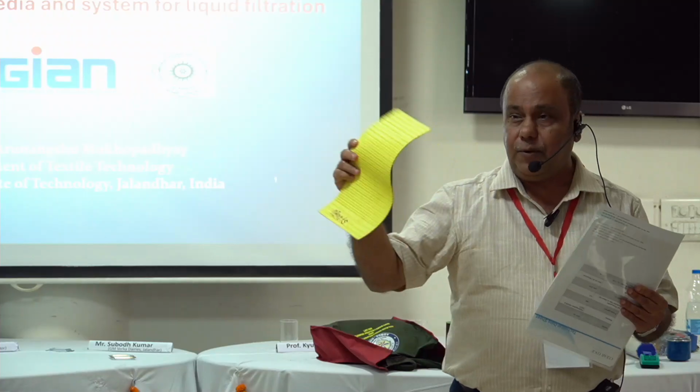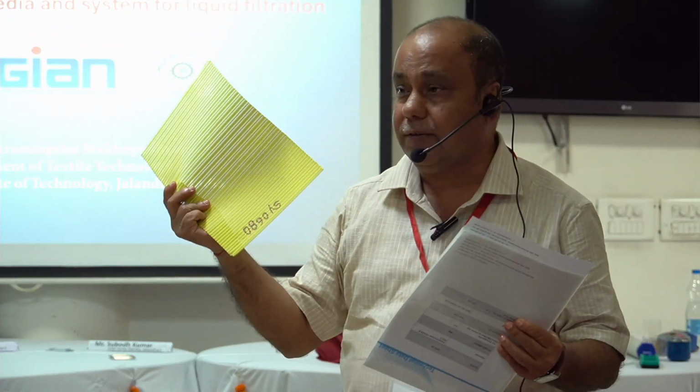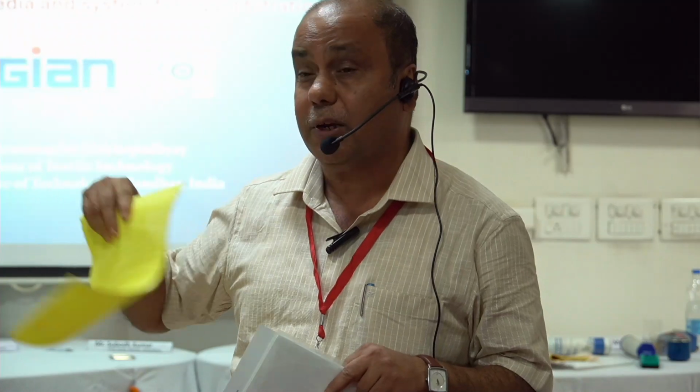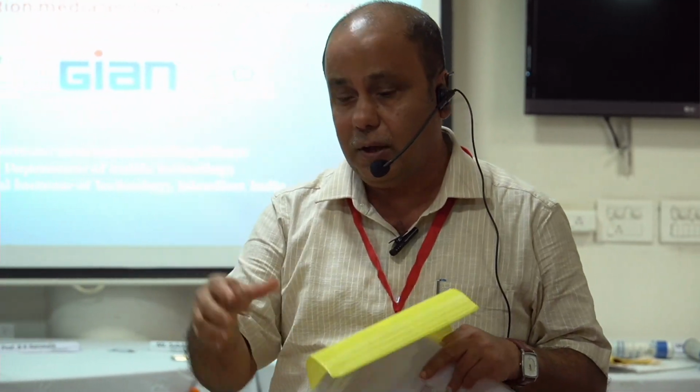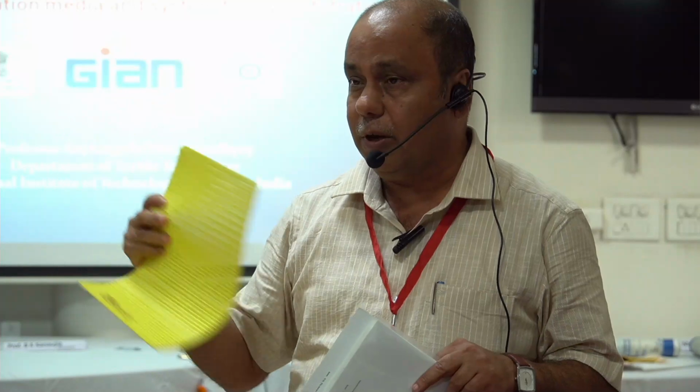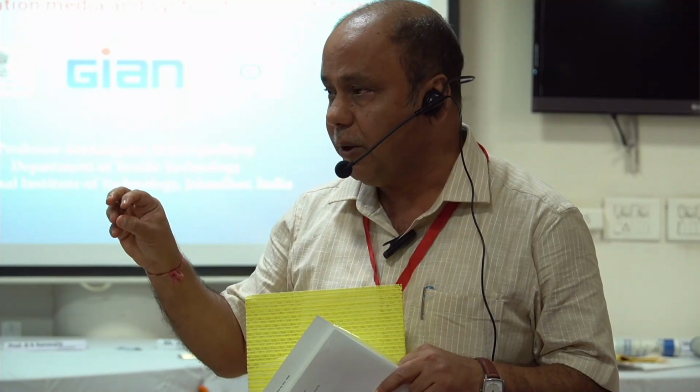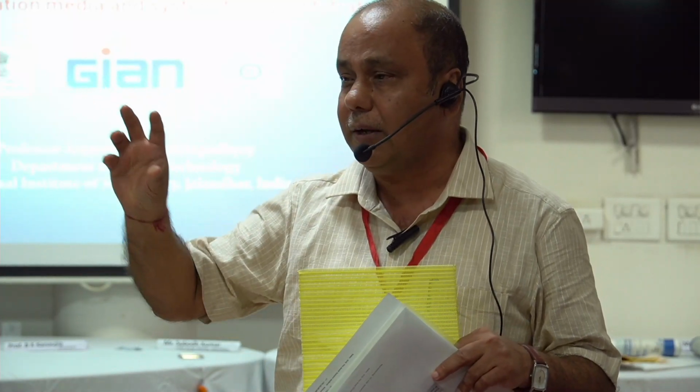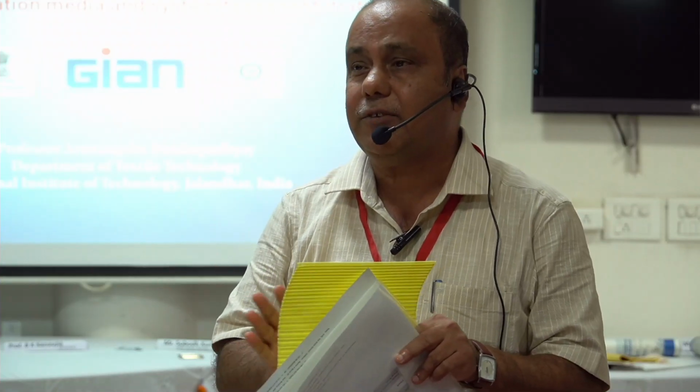Now this one is a liquid filter fabric. If you see, the size of the particles is large. Normally in air filtration we don't talk about large size agglomerates or particulate matter. But in liquid filtration we go for a large size of particulate matter, which can be conveniently addressed, because you should not unnecessarily reduce the size of the pores to capture large particles, otherwise the flow will be restricted.